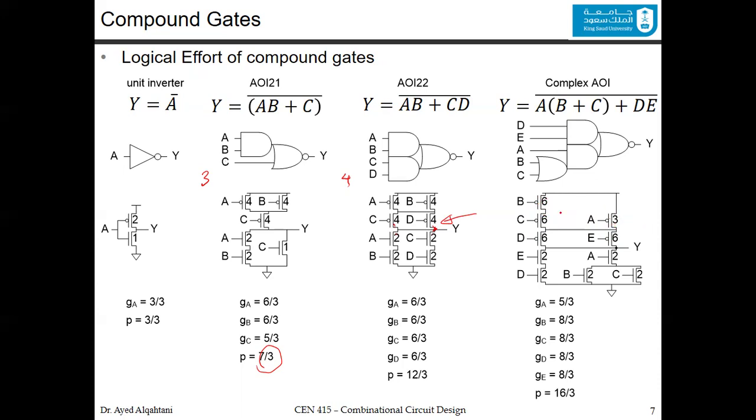But to give you a mathematical way to do this, just count the number of transistors here and say that there are 2, for example. The number of transistors here is 1. Now, you know the sizing here is 6, and you want to find the sizing here. Let's call it x. So what's the value of x? It's 6 times 1 divided by 2, which is going to be 3. If you apply this rule, no matter what circuit you have, you'll get the correct sizing.